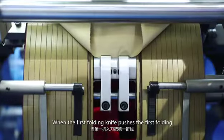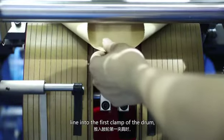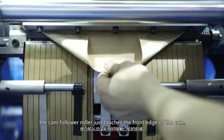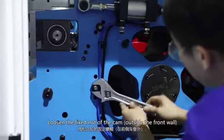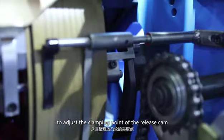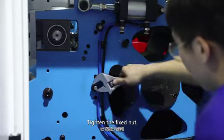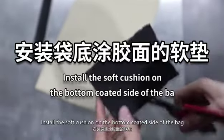Release time of the center finger. When the first folding knife pushes the first folding line into the first clamp of the drum, the can follower roller just touches the front edge of the can. Loosen the fixed knot of the can to adjust the clamping point of the release can. Move the can to the correct position along the positioning pin. Tighten the fixed knot.